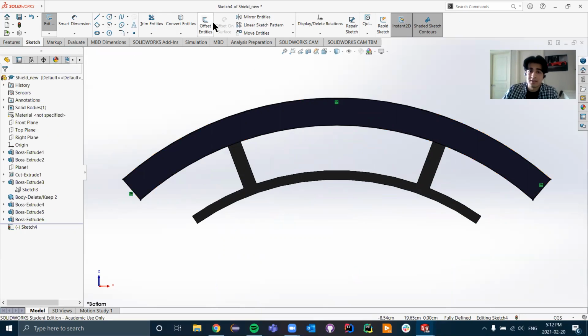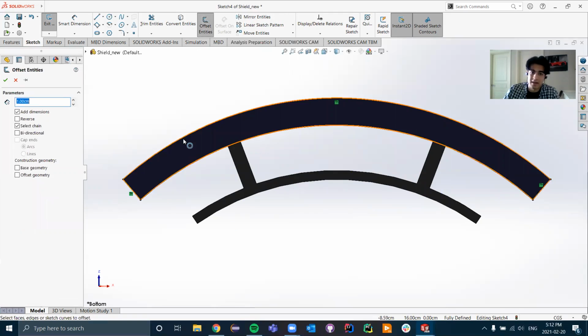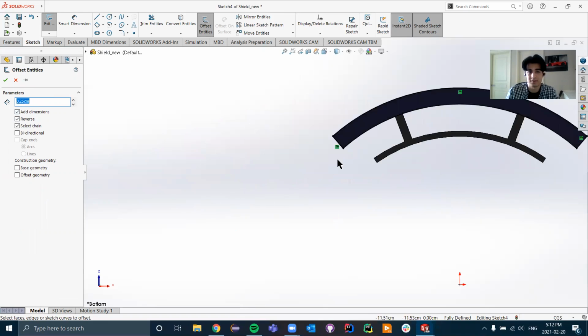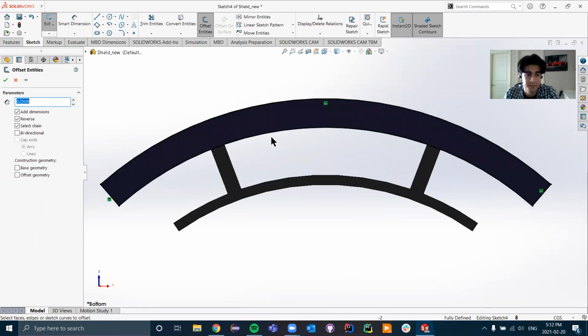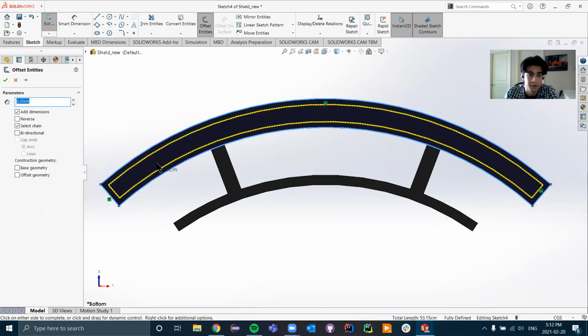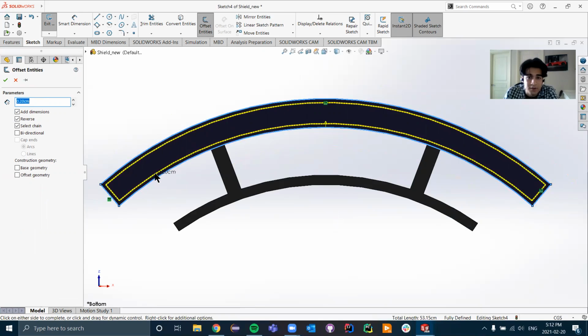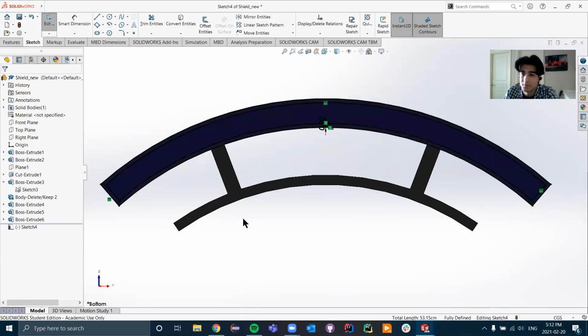Now, the intention of this is to actually offset these edges a little bit. So what I'm going to do is click within the closed contour that we just created and offset it by 0.25 centimeters. So I think you just got to give it some time to, yeah, it didn't select for some reason. That's okay. Ah, perfect. So it's automatically selecting for us. I think for this region, 0.2 centimeters inside would be perfect.